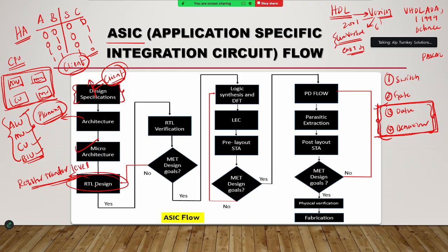Next, RTL designers will design these modules, the micro architecture like ALU, MU, or they will design the small units also, but the foundation is digital only. The ALU they will design using combinational circuits, and the memory unit using sequential circuits. If you are strong in digital, then you can write the Verilog code. You are describing your digital circuits in textual form, that is nothing but RTL.